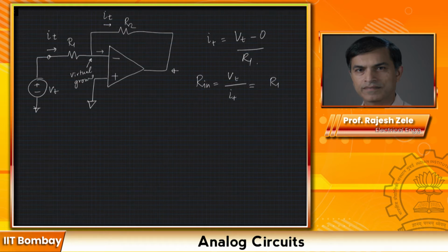So the key thing to note here is, if you look inside this amplifier, the model shows Av times (Vp minus Vn). So this is a voltage source. Now the voltage source doesn't matter where it's connected. For example, it's connected to these resistors and all those things, right?